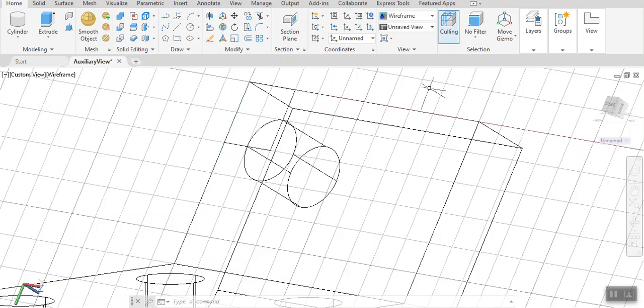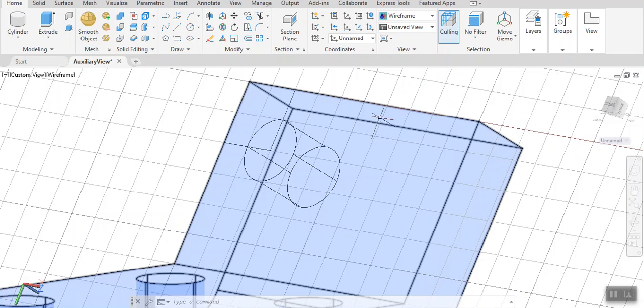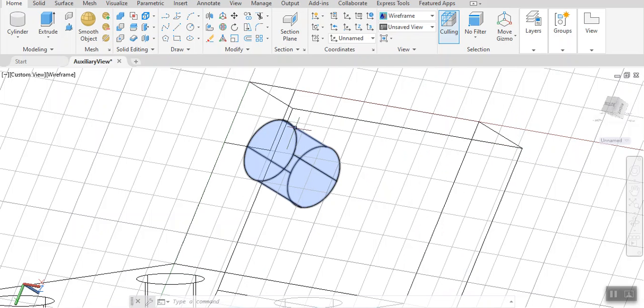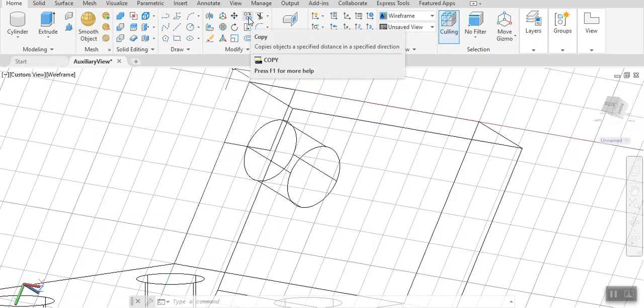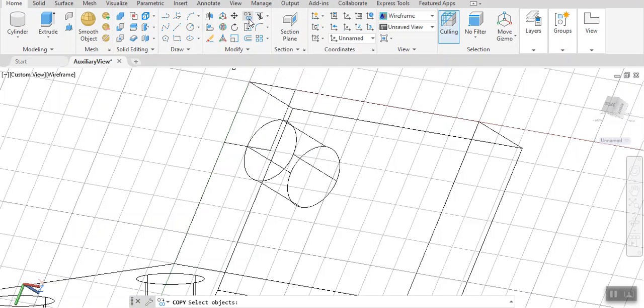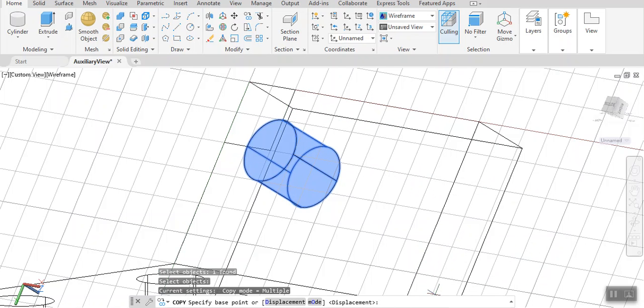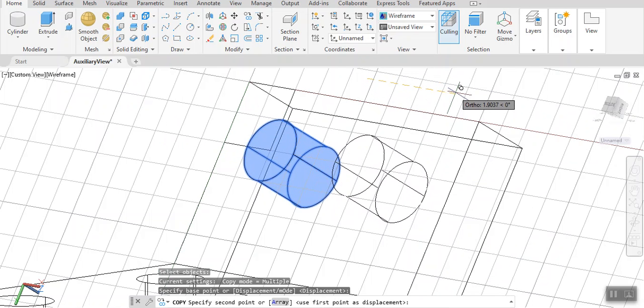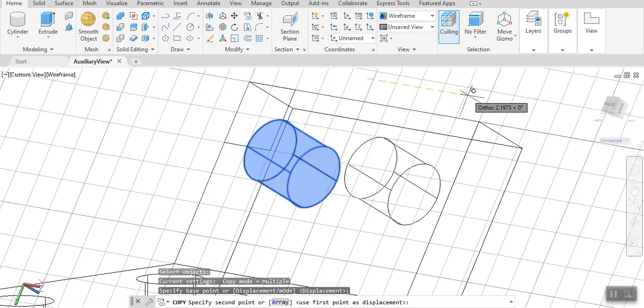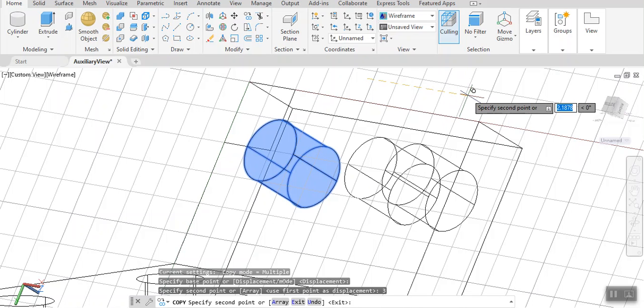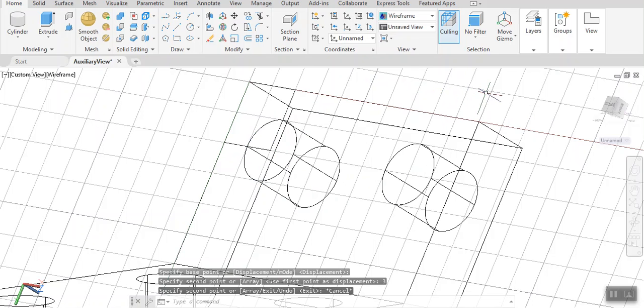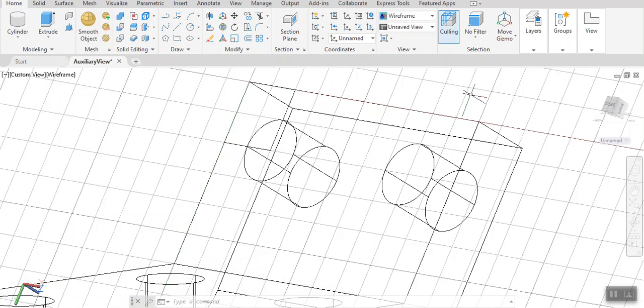Next, and this will be a hole. And I'm going to offset the second one. How far is it going to be? 3 inches. So maybe I should use copy command. So I move my cursor over the copy command on the ribbon and select the item, enter, move my cursor with the ortho on, pick any point on the top, move my cursor to the right, and type 3. I'm typing 3, enter, and escape. So next line is also created. Next point is also created. Good.